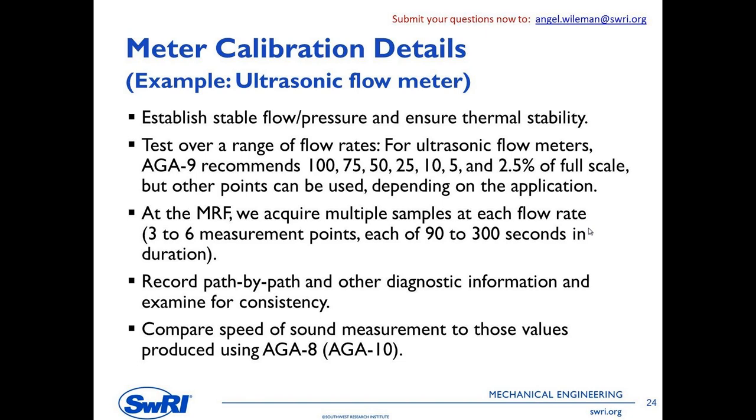Characterize the range that's going to matter to you the most. If you're going to utilize the full scale range of the meter, then by all means calibrate it over the full range. We know some people that calibrate it past the full range just in case. That way if they have some event where they need to go beyond the quote-unquote full-scale capacity of the meter, they can do that as long as the meter tolerates it.